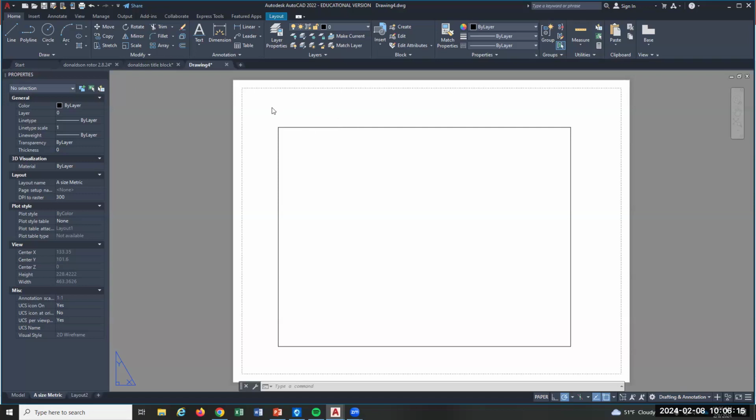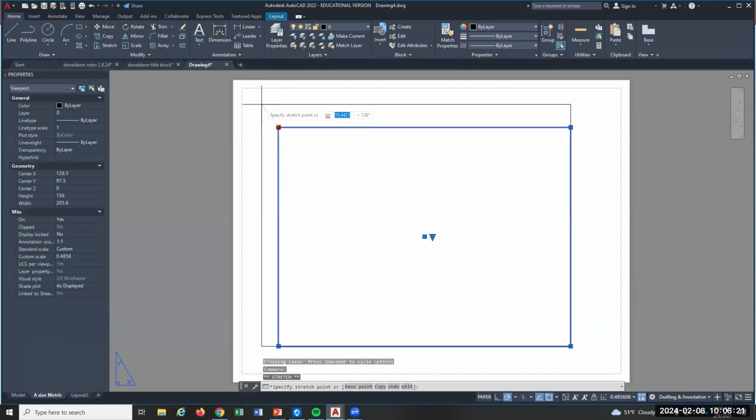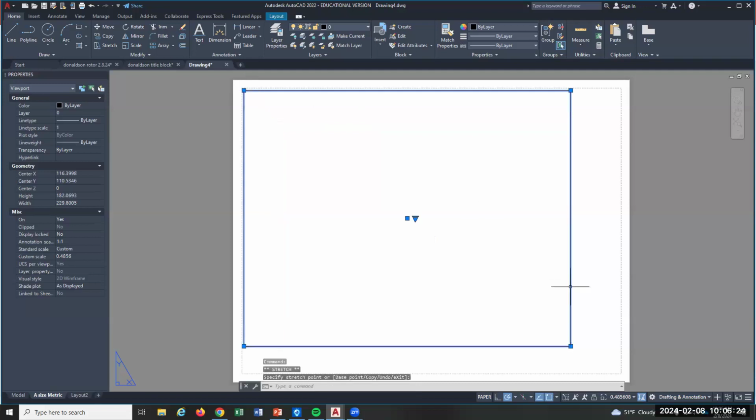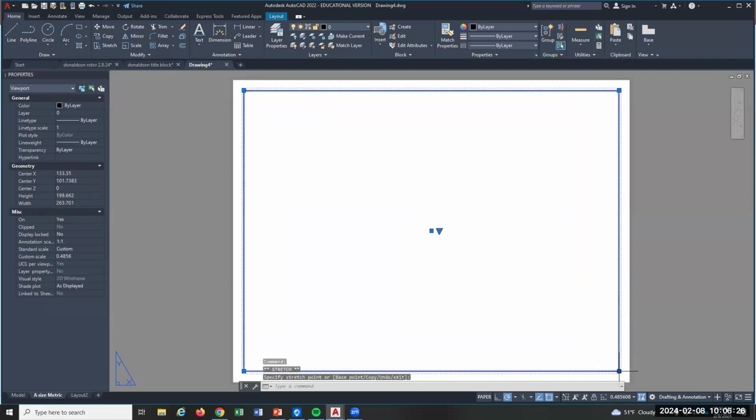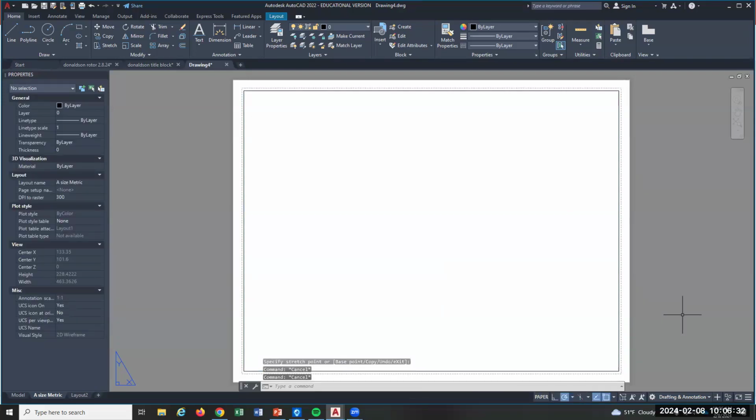And then this is the viewport. We talked about that, right? So the viewport needs to be dragged out. And the dotted line is the printable available space. So open it up so you have the most space available for your drawing. Okay, so that's metric. When I save this, I would typically put a metric notation in the saved file name if it was me. Because when I go back to get that file 2 years from now, I won't remember the metric or whatever, but if it says it right in the file name, that's helpful.